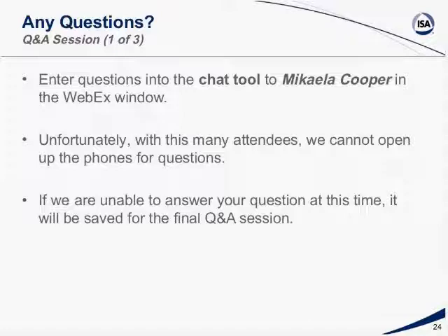Okay, next one. What is a good practice related to the amount of data to perform a benchmark? It's pretty much, and we're going to talk about this during the bad actor portion of this, really, you want all the alarm data because you want to baseline things, and then you can benchmark from there. And with the tools available, it really becomes very convenient to accumulate large amounts. Now, when we talk about bad actors, we did a 5-day survey of a facility that had approximately 350,000 alarms in those 5 days.